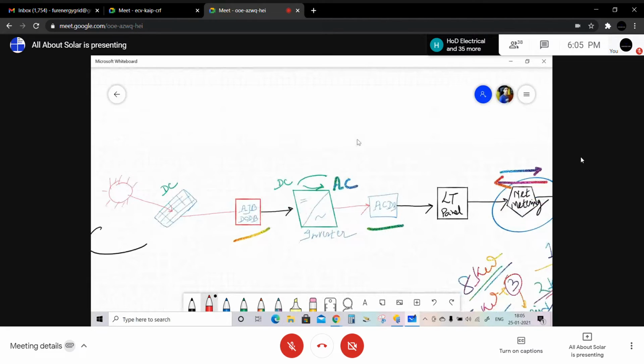First of all, let me tell you about the on-grid system. For a solar plant, we connect the solar module with a particular load. Let's say you have a residential load, or you are running an industry. We connect the solar plant with the inverter, and then you can connect it with the load, as you can see here. As solar irradiance comes to the solar module, it goes to a specific device called the ACDB or DCDB. This is called the DC distribution box, where the power flows first, and then it comes to the inverter. This is basically the overview of an on-grid solar plant.